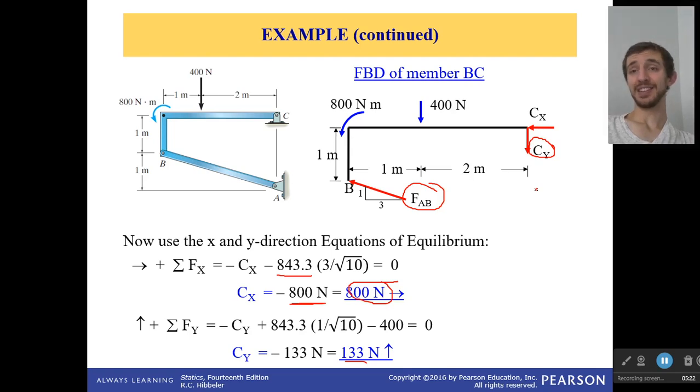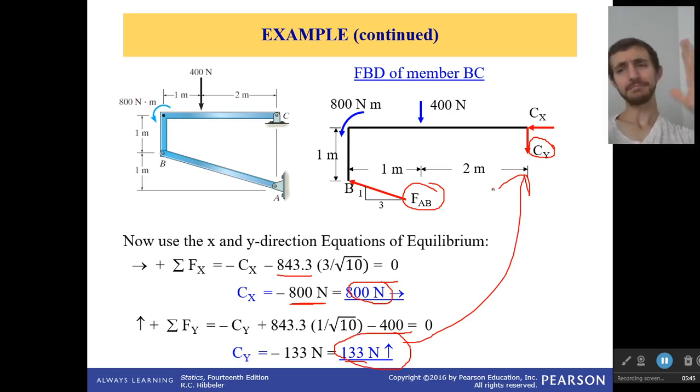Just be consistent. Don't randomly switch arrows halfway through. Get your negative sign, and don't go back and change the free body diagram. Just say, okay, if I have to give a direction, I was pointing it down. Since it's negative, it's actually going up. You can write that next to your answer like they do here. I would not go back and flip your free body diagram, because you will probably confuse yourself if you start changing numbers. Maybe you won't, but it's something to be careful about.